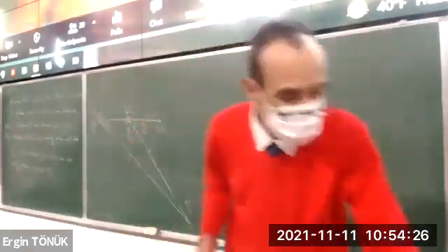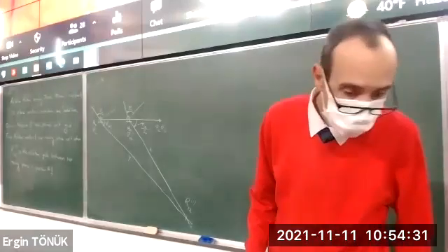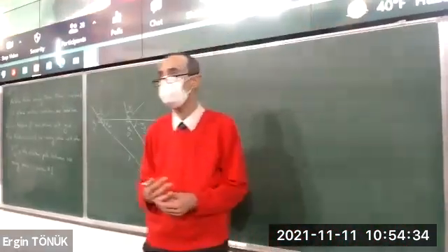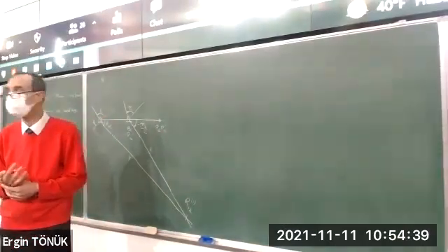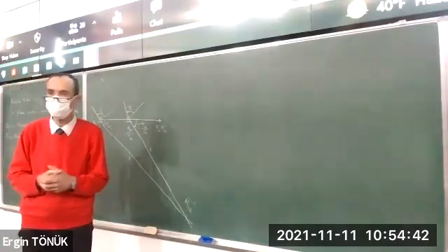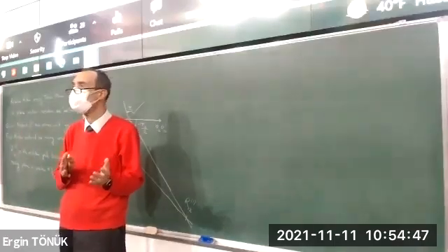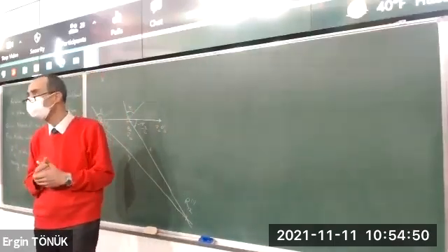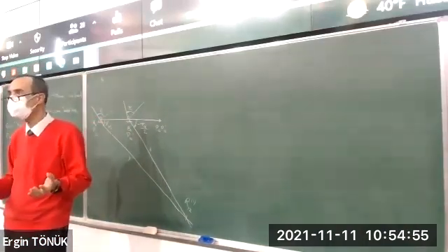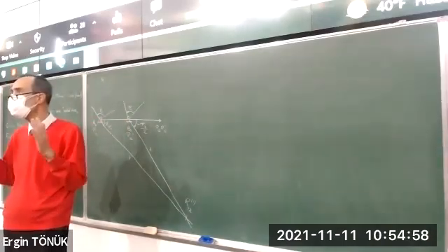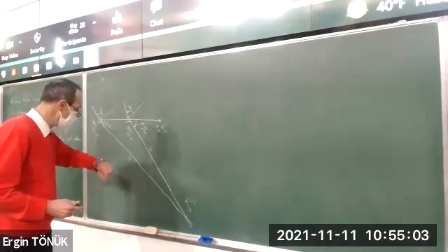So we have the design procedures, and actually these 3 procedures have different parameters. That's why we have them. And actually in the 3rd procedure, we can also optimize the transmission angle. When we say optimize, actually the transmission angle at 2 extreme positions of the mechanism are equal. So that's called a minimax optimization. It's not the real optimum, but you equate the deviation from 90 at the 2 ends. Okay. So let's start seeing procedure 1.